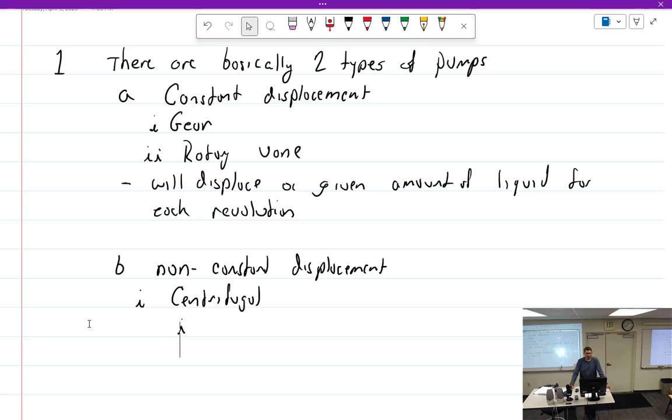So you have on the engine the rotary vane type pump, typically. And then somewhere on the airframe, maybe even inside the tank, you would have a centrifugal. So you put it inside the fuel tank, centrifugally pump fuel out. If you block off the exit, no big deal. Doesn't hurt anything. It uses that pump to pump everything up to the rotary vane. The rotary vane is constant displacement, pumps it to the fuel control unit.